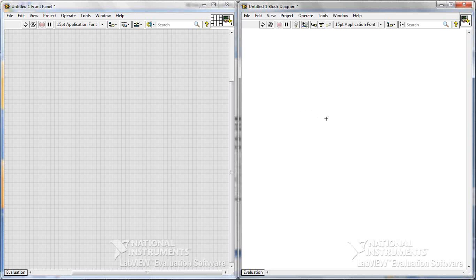Now I have my sensor in place and it is acquiring some data. Now I want to log that data into my PC, or I want to see that particular data on my PC. So the hardware I have right now with me is NI myDAQ. Now this NI myDAQ is plug and play, driven by USB. This doesn't require any external power supply. It takes its supply from my computer.